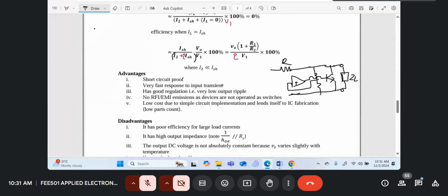So what I'm trying to say is, if this voltage, supposing it was a constant regulated voltage, suddenly spikes up to something else, then this spike will appear here suddenly, because this resistance is not very high, so it doesn't have any time constant.